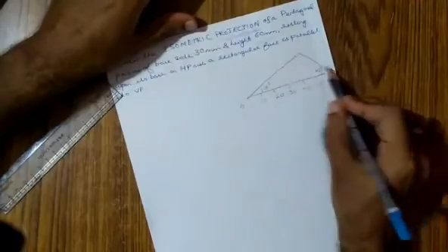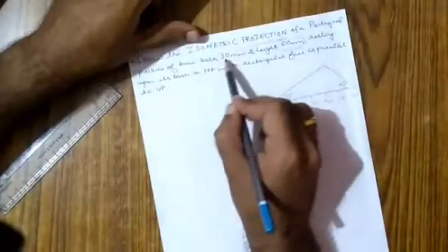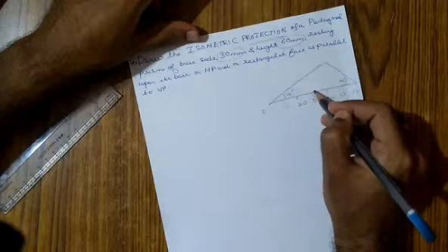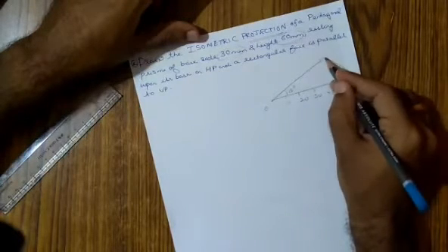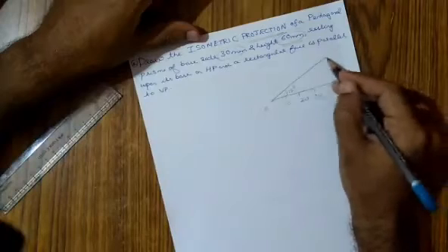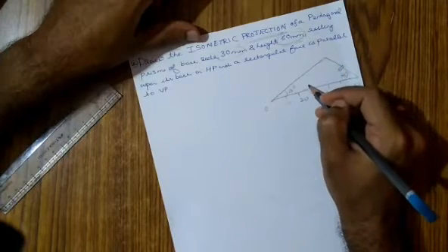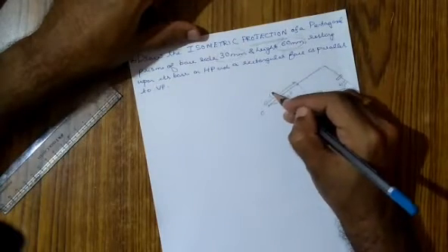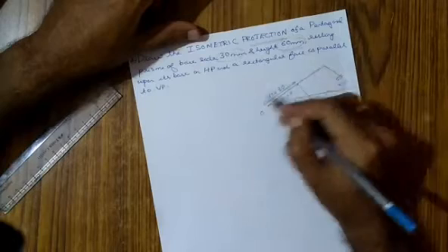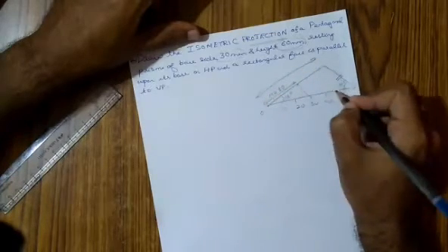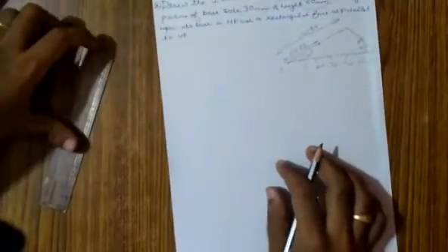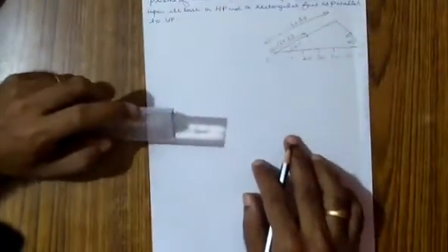So 60 is one dimension which is coming in this question, and the second dimension is the base side of 30 mm. In order to get the length ISO 30, based on this edge, this side, you have to draw a parallel through 30 to meet this adjacent edge. So this length is going to be your isometric 30, and this full length will be your isometric 60. So let's draw the isometric view first.